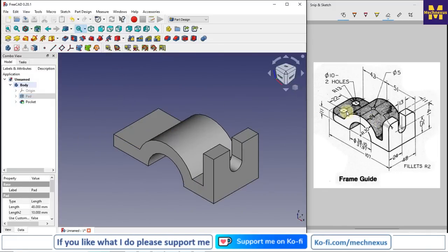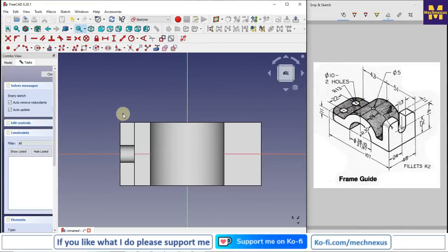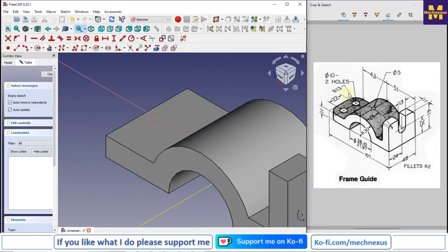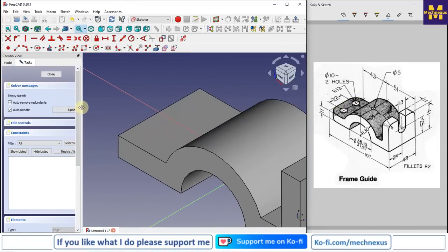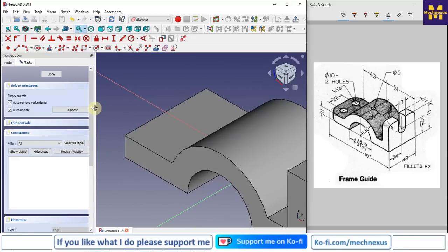And then we will adapt these 2 holes. So I will select this face and I will say sketch. So it is a blind hole, so I am going to make it with cut, or you can make it with hole also.